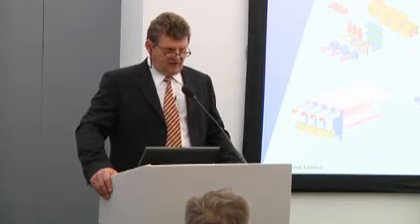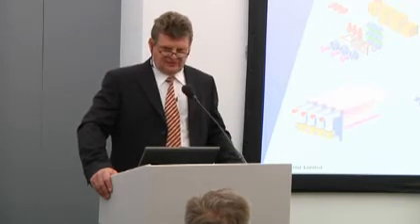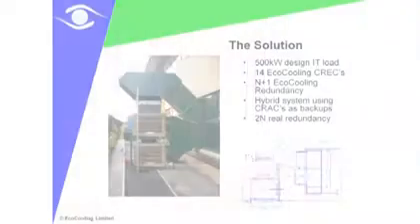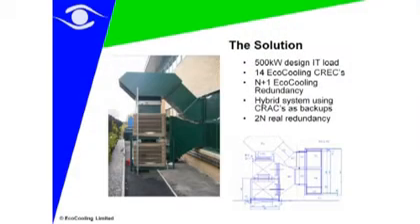Now many people have existing data centers with legacy equipment and require retrofit. So we have to have a number of installation methods to implement this. And this is what we actually ended up with. These are two stacked coolers sitting at the bottom there, with side discharge coolers pushing air in through a removed window and allowing the duct to go in there, which then goes into the raised floor. The top duct is air which is returning the hot air from the hot side of the data center.